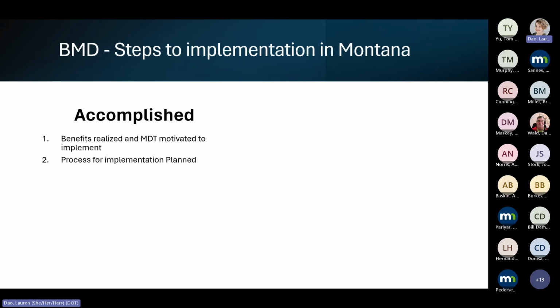What we started in our specification many years ago was to give you the acceptable range of volumetric targets. You pick a target that's in that range, and then you try to achieve your target instead of trying to hit the mid-range, to promote consistency. And we'll control it with our performance test, the Hamburg.